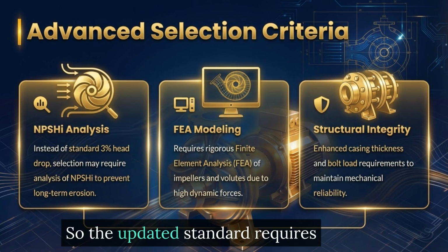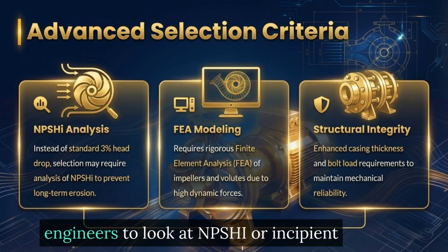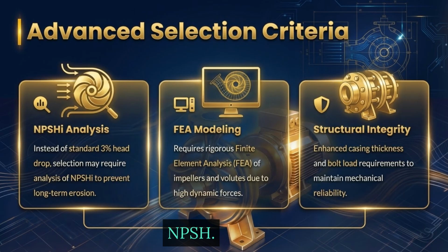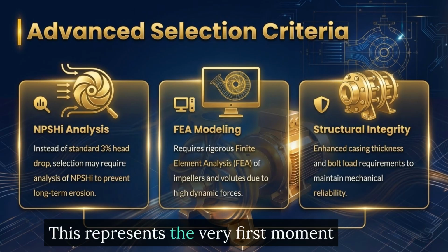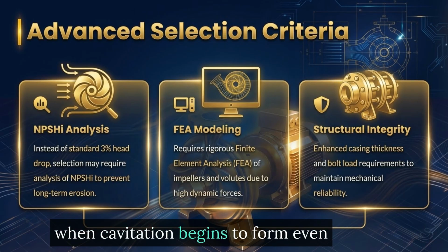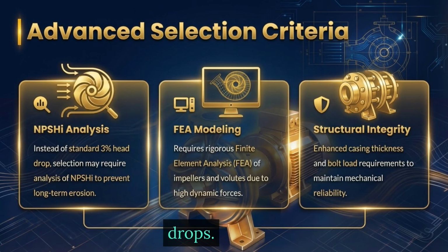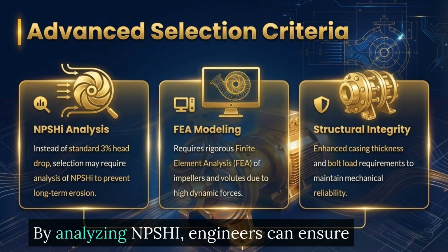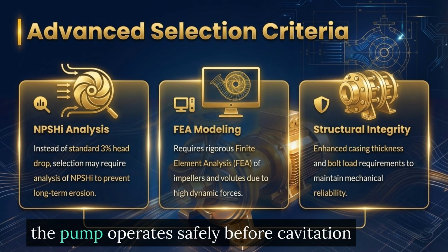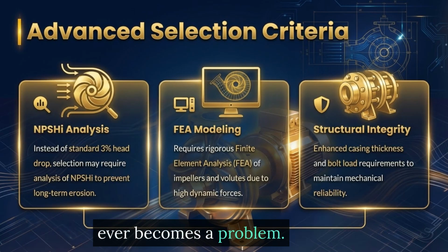So the updated standard requires engineers to look at NPSHi, or incipient NPSH. This represents the very first moment when cavitation begins to form, even before the pump performance visibly drops. By analyzing NPSHi, engineers can ensure the pump operates safely before cavitation ever becomes a problem.